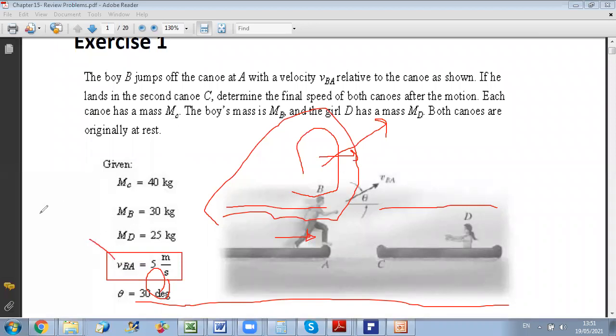But please note, in conservation of linear momentum all velocities are absolute. Okay, so let me just write: in the linear momentum equation, all velocities involved in this linear momentum relation are absolute velocities. So I should link the absolute velocity of B to the relative velocity given. We know from chapter 12 that relative velocity can be used to relate the two velocities.